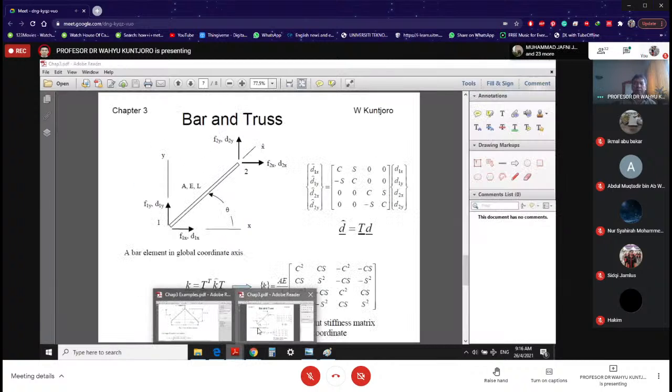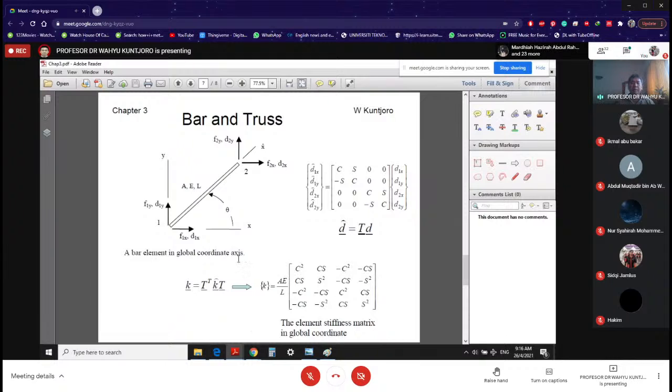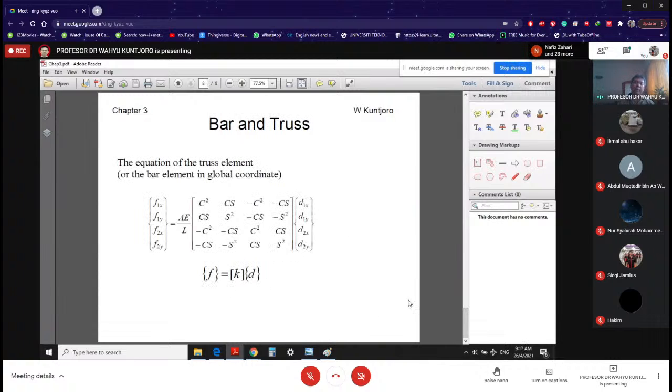And so the way we calculate our element equation is going to be based on this. You need to know your theta, you need to know your x local axis, and then at each node, you'll have two displacements and two forces. That means your equation is going to be based on this equation. You have the force matrix, you have the displacement matrix with the relevant nodes associated with the element, okay?